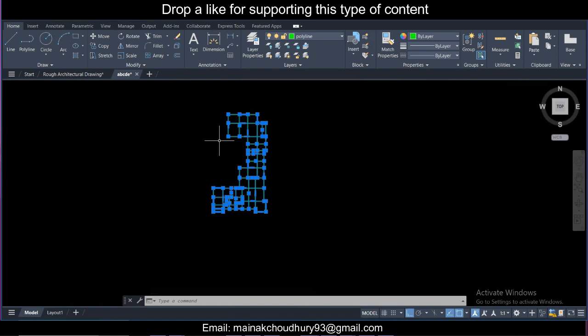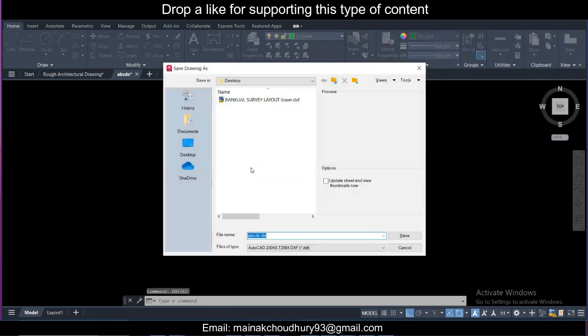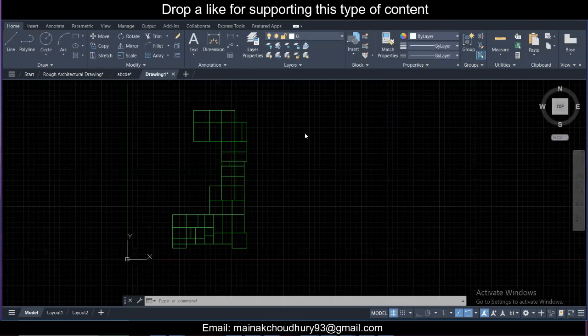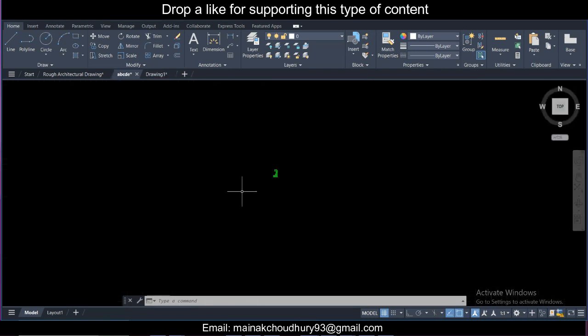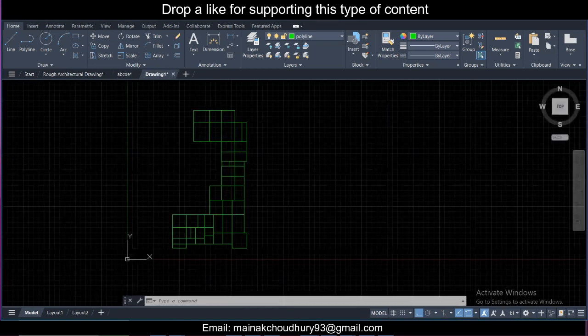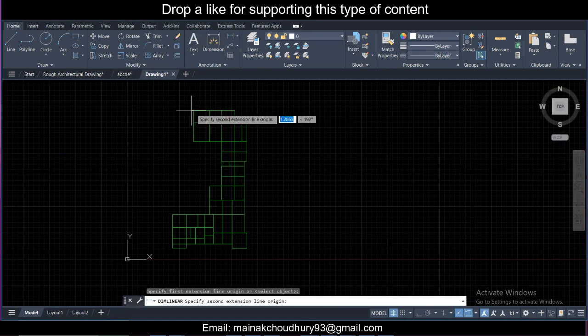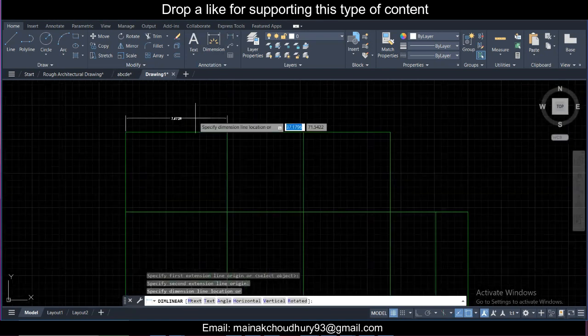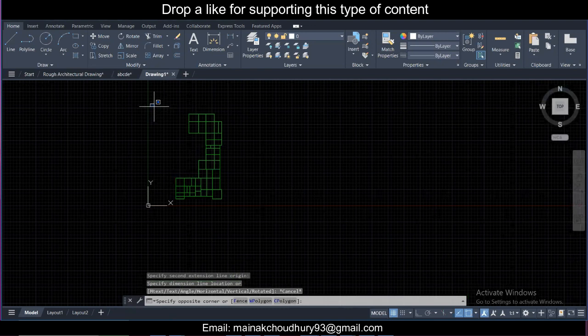So this is the file which you can convert. Just select this, and then click on DXF out, and this will be saved. So just save it in a particular location, or you can open a new file and then copy this file from the other one and set the units to meter, and then copy the file to here like I've done. And then after that you can delete this file which is in mm. Okay, so this is the file in meter, and you can see the units here. This is in meter. Now this can be imported in STAAD.